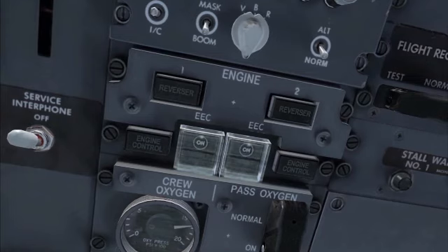If the light does not extinguish for 12 seconds or more, a malfunction will have taken place and a master caution will present itself. In either reverse thrust setting, it is not recommended to allow the aircraft to decelerate below 60 knots with the reversers deployed, because of the risk of foreign objects injecting themselves into the engine cowling and damaging components. To provide system protection in the case of thrust reverser uncommanded motion or incomplete stowage, an auto restow system compares actual reverser position versus the commanded position and stows both thrust reversers back to their fully closed position.